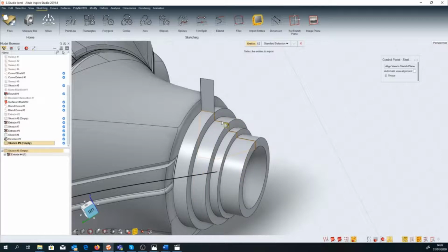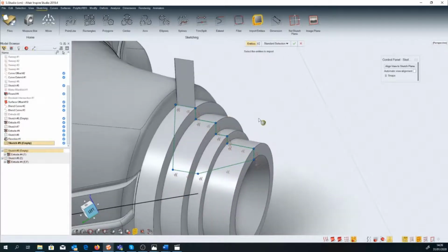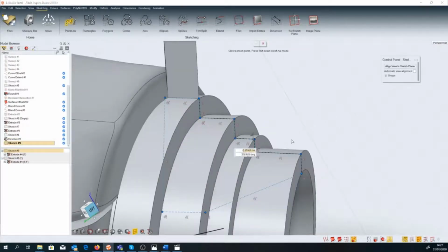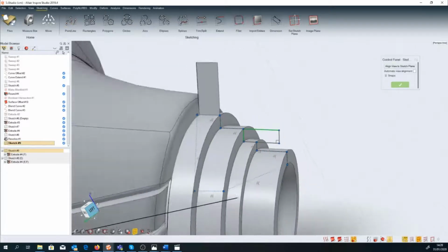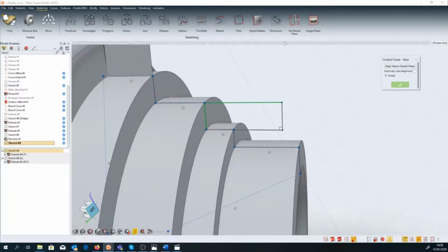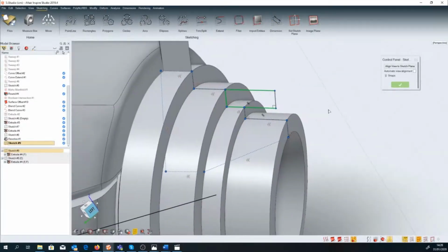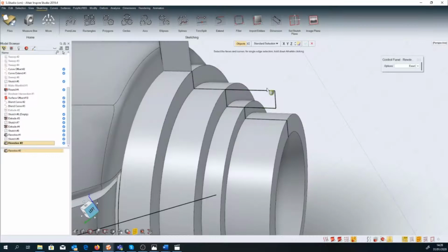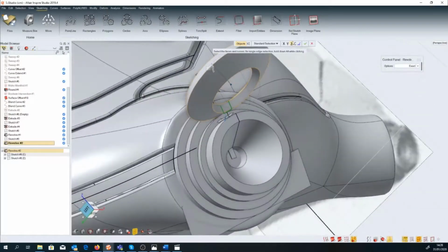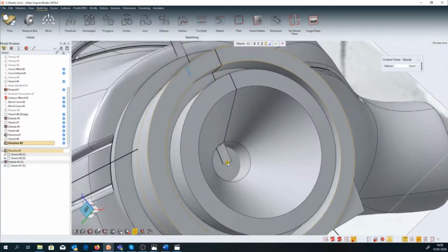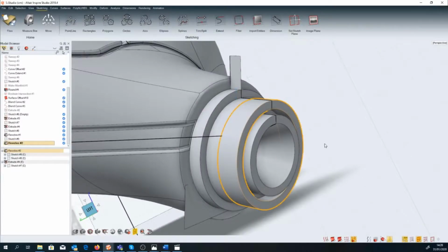We will need the final element to complete the filter, so I'm going to create another sketch on plane perpendicular to the center surface, and I'll revolve the geometries around the axis to create a ring. Now I'm going to select revolve and select the axis.